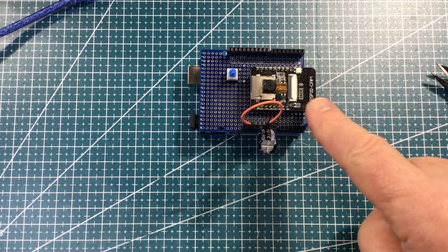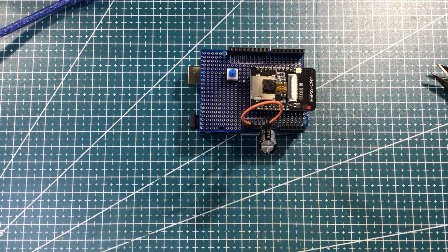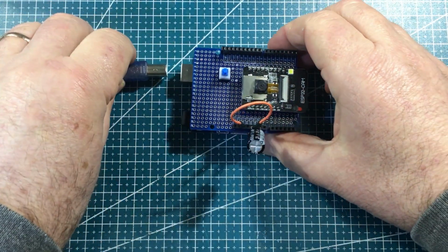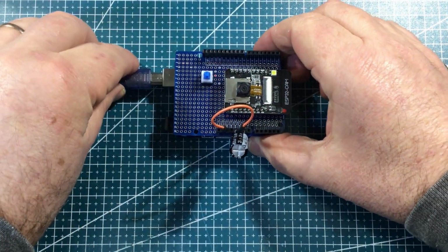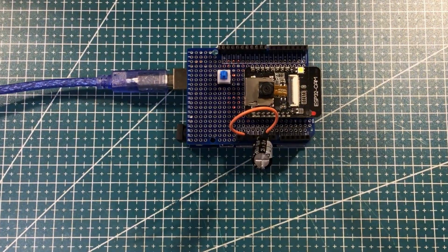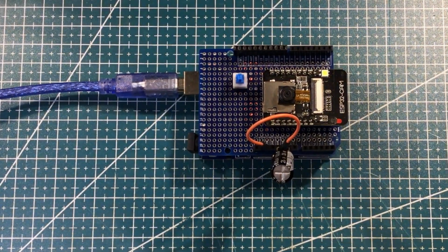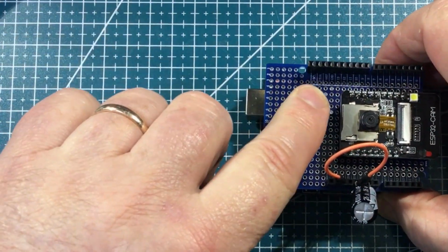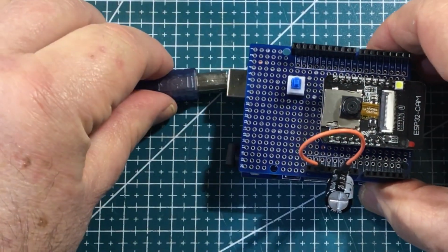So now, this is the original ESP32 that I programmed before on the breadboard. So it should, if this is, yep, that's just normal mode, it should, when I connect it, just flash at 1 Hertz as programmed before. Yep, good, nothing blown up, that's a good thing. So now what I'll do is I'll pull that out and I'll put it into programming mode and put it back in again.